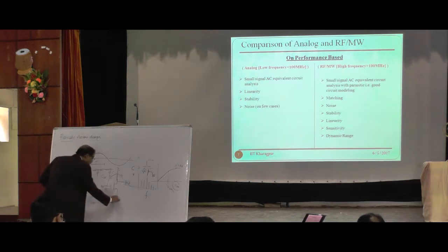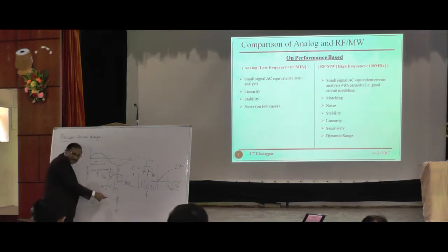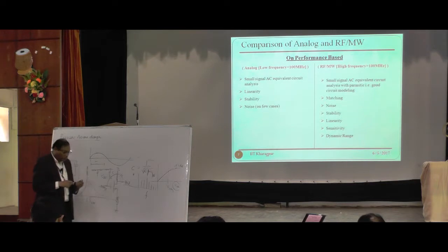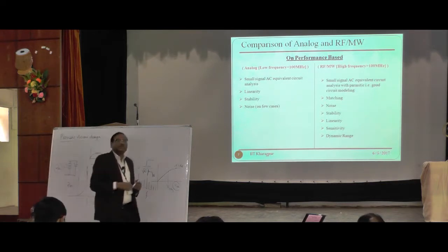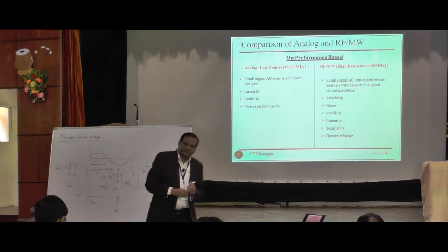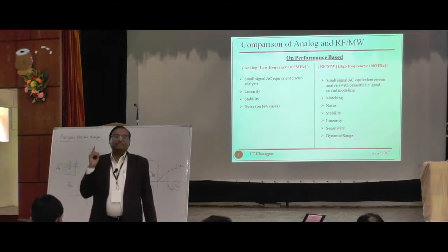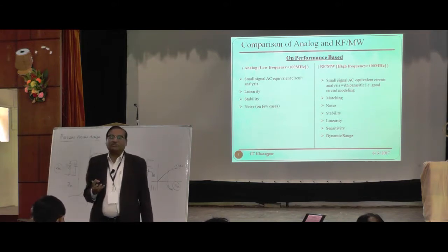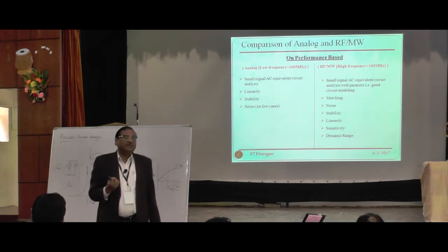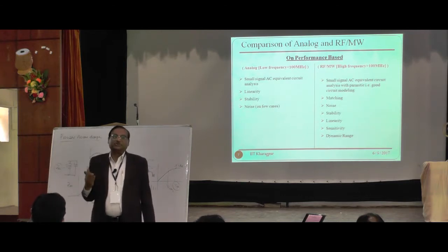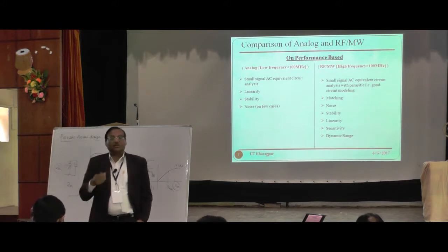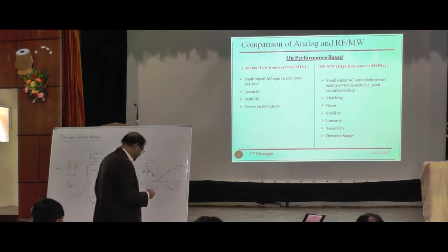Knowingly means you remember that you have a resistance or inductance at the source. You know that there is negative feedback from the first year classes. So that feedback will come to your input. So there will be a known path of feedback, and those will create instability in the system. So S is the stability parameter that should be greater than 1. For an amplifier, when you talk about linearity, like 1 dB compression, and gain in dB, there must be stability calculations. It should be as high as possible, right? And that will not come freely. So you have to compromise with something.